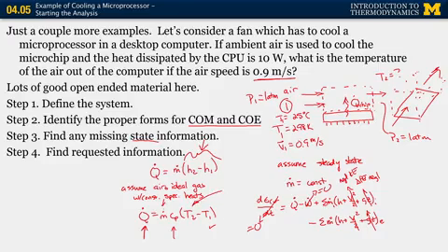We look at these variables in general, we say the specific heat at constant pressure is a thermodynamic property. It's a constant specific heat, so we can define it at the entrance state conditions. In principle, this sounds pretty straightforward, that there's not a whole lot left for us to do. In practice, it's much more complicated, primarily because we don't have those convenient lookup tables in terms of enthalpies.